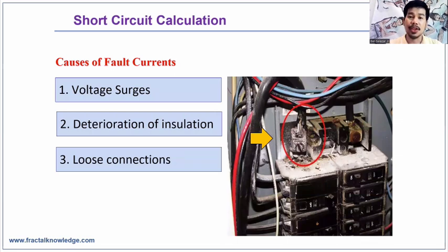The third cause is loose connection. This is common in our electrical system. When there is a loose connection, a hot spot is present. When not corrected, a hot spot can burn the insulation of nearby wires, and when insulation breaks down, then short circuit is likely to happen. It should be part of your maintenance program to inspect loose connections, or if you are doing an electrical audit, look for evidence reports that hot spot rectification is done or IR scanning was done twice a year.